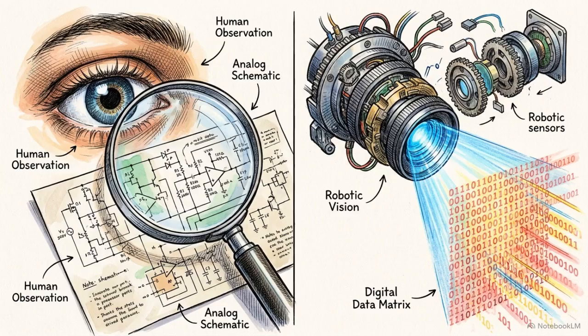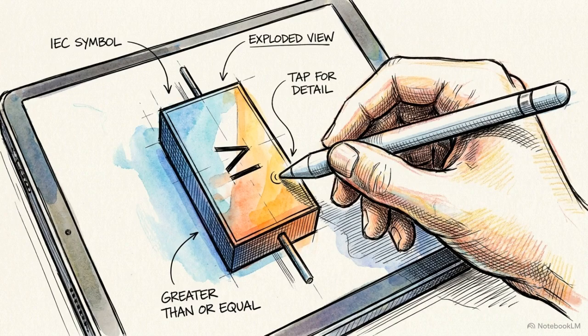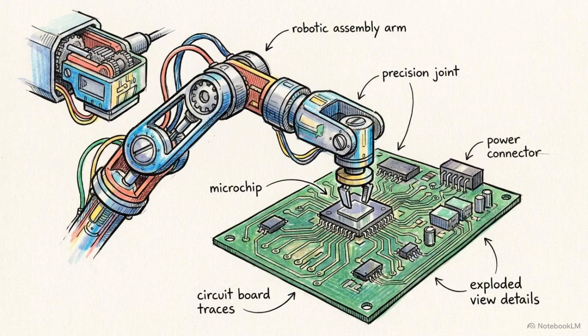To achieve this, TC3 employs a bifurcated engineering approach, managing representations for both the human eye and the machine parser simultaneously. The human sensible representation consists of the IEC 60617 graphical symbols. The machine sensible representation operates entirely out of sight, governed by the IEC Common Data Dictionary.